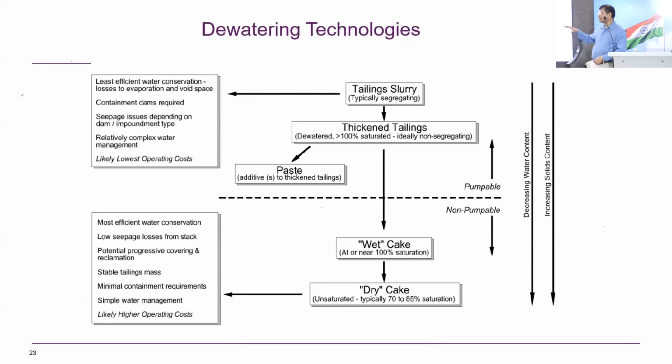I will give you, like we have a slide also for the earthquake on these things. I will show you some examples there. It all depends on how much moisture content there is, how saturated the tailings are. If it is fully saturated, then you are good. But the problem comes when they are partially saturated, like 80%. I will show how the partially saturated state causes more damage to the tailings.